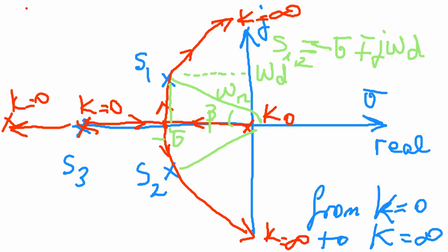So as a result, when you change your value of K from 0 to infinite, your poles, means the roots of the characteristic equation, are changing. When they are changing, you are able to select the best design point for you, best design K value for you. Of course, we all know that by looking at the stability part, you are not absolutely free to increase the K value.